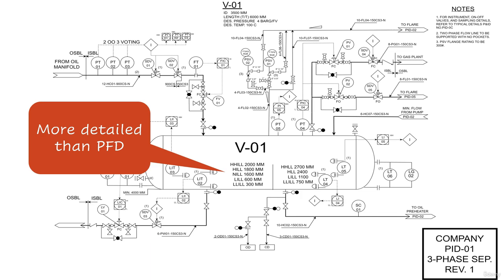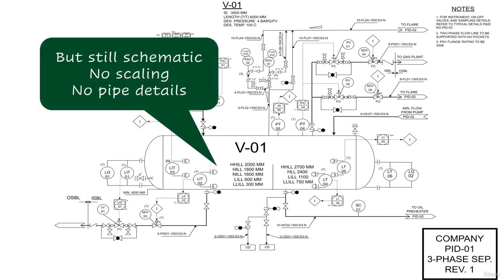Although it's a schematic drawing at the end, so no need to consider scaling in the drawing, neither do we consider the line distance or elbows or supports in the P&IDs, as all these are considered in detailed piping design based on the P&ID and 3D model requirements.